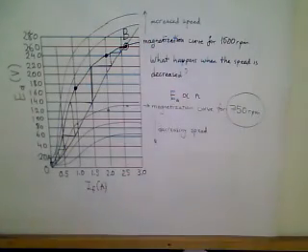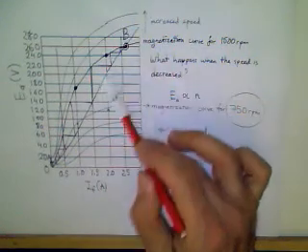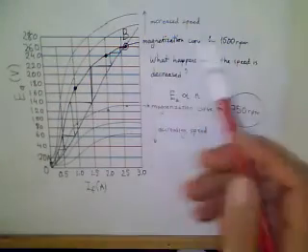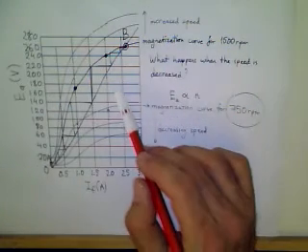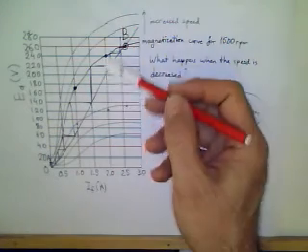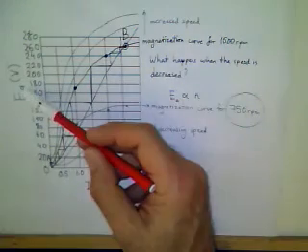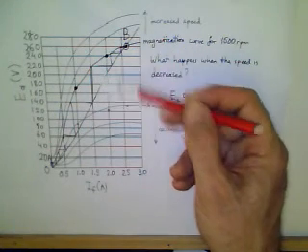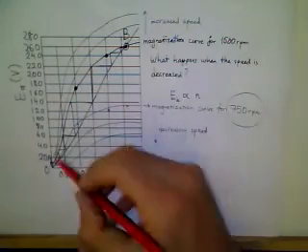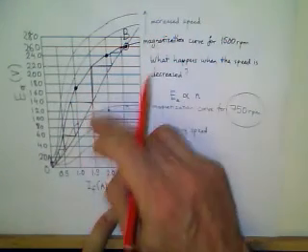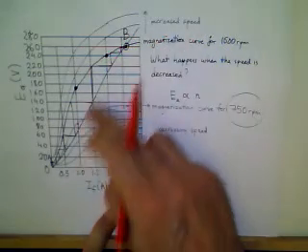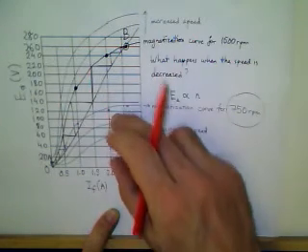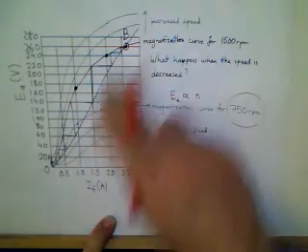So for part B, we consider for the same RF, when the speed is varied, what is the minimum speed to induce self-start? If we increase the speed, we increase the induced voltage, because induced voltage is directly proportional to the speed. If we decrease the speed, the induced voltage drops. Following this curve, the voltage drops at some points,